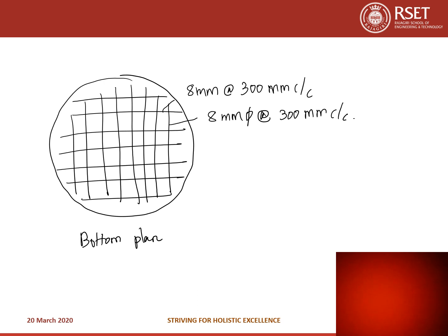Here we don't actually require circumferential reinforcement, but still it's good practice to give at least 2 rings of circumferential reinforcement.